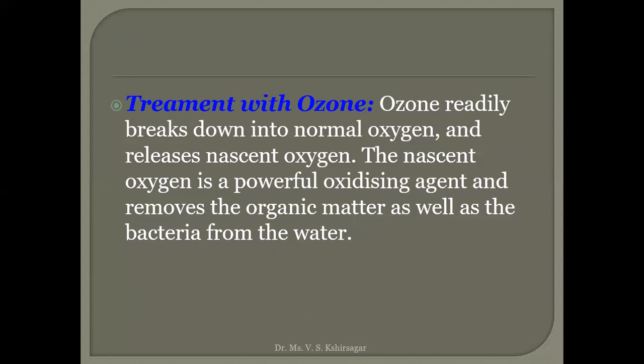Then it releases nascent oxygen. The nascent oxygen is a powerful oxidizing agent and removes the organic matter as well as the bacteria from the water. So this third method for the killing of bacteria is ozonation. Please note down ozonation.